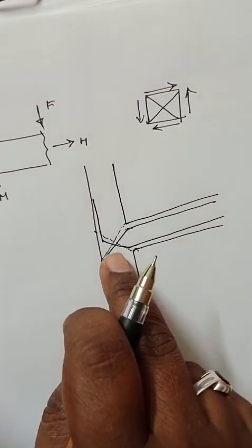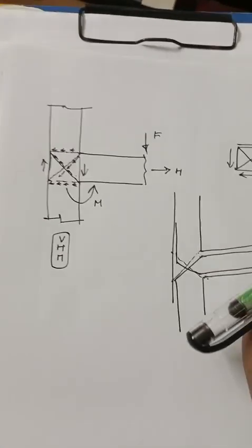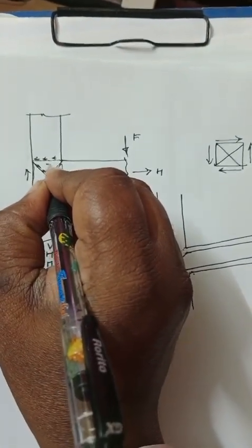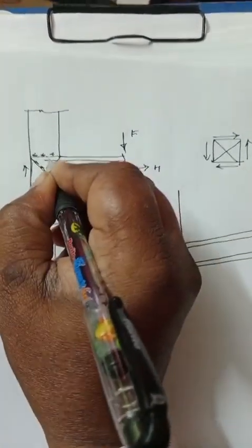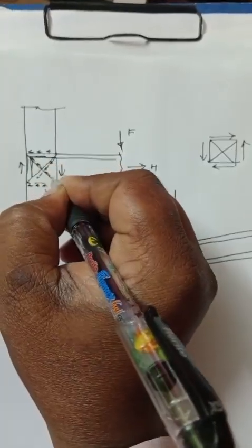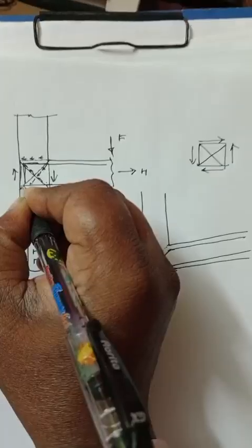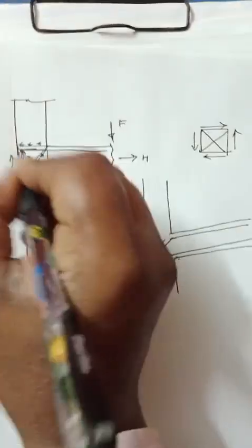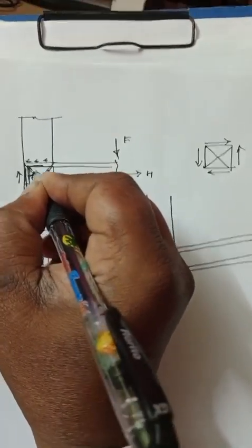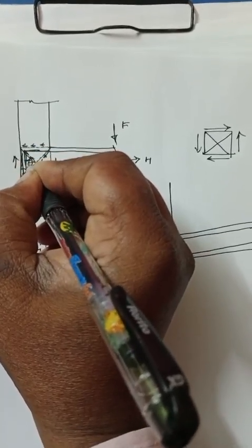But ideally, this is not possible all the time in a junction. It will take a lot of time, and fabrication is also not so easy. So it is better we provide the right angle hook. Here you draw this, you provide the hook here and bend down. You should cross and touch this plane, and one more, it should go and not touch this, and you should proceed. This makes the angle, say theta. This is the contributor towards the shear resistance.